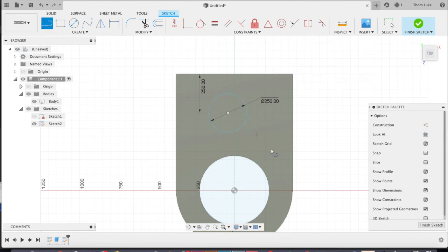With this one, I'll show you a trick. I'm going to draw a line off the origin, and this line, I'm going to make it for construction. When I make for construction, that means that the modeling software automatically knows I'm not trying to do a feature with this piece of line work. This is purely reference for other bits of my geometry.